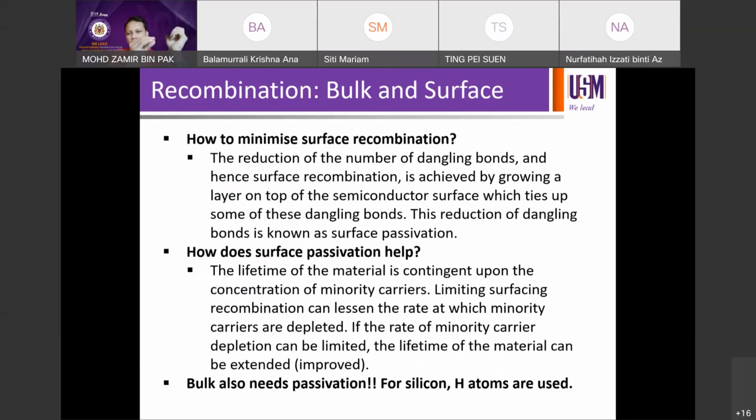So how do you fix that? Is by passivating certain atoms to the dangling bonds. You are actually saturating the bond. Or you close the bond, you lock it, you don't let it dangle. So the moment you lock that or you saturate the bond, we call it technically saturating the bonds or passivating the bonds if you like, then you are doing surface passivation on the surface.